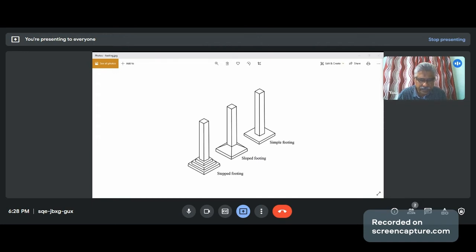And you know, bearing capacity is a type of pressure carrying capacity of soil. Our footing will be exerting a pressure on the soil, and if that pressure is less than the bearing capacity of the soil, then our footing is safe. Also, you know that we will apply some factor of safety to the bearing capacity value, which you must have studied in the geotechnical engineering class.